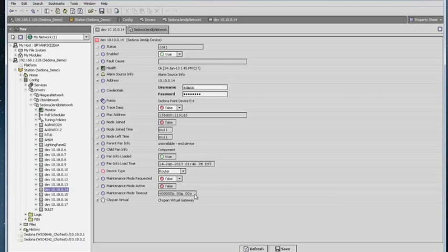Now, the difference in a true mesh and a tree network, which is what we utilize, is that a mesh network, a true mesh under Zigbee protocol, has a limit of about 120 devices. In a tree network, which is what, again, we utilize, you're not limited to the 120. You're upwards of 500 devices. So what you're able to do in a star or tree network is create a network where all the devices still repeat through each other, but they're not listening for every other device as in a true mesh, which is better for a controlled environment because you don't want excess overhead.